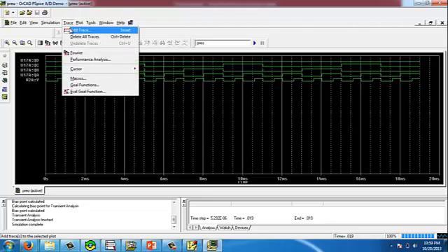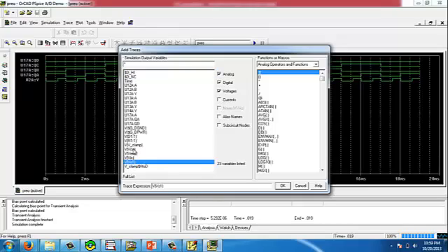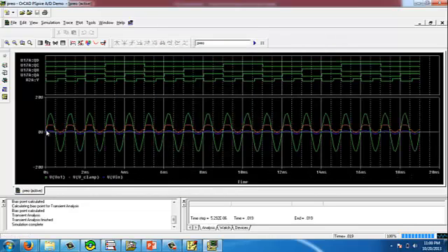Now when we put the trace of all the sinusoidal voltages that we have attached to prove our point, we get V01, which is the voltage after the operational amplifier. Vin was the supply, and V clamp was the output from the Zener diode. As seen, the supply voltage is a plus minus 1 volt sinusoidal voltage. The output of the operational amplifier after multiplying by the gain of 11 will give us an output of 11 volts, while the output from the Zener diode will be plus 5.6 to minus 0.7 volts.